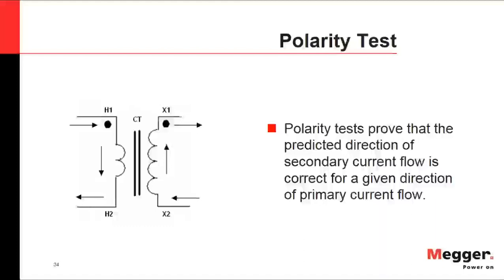or the fault will be created without a real fault in the system. In the metering environment, just imagine that you are power generation and you're transferring energy from power generation down to transmission. And if you have an inverse polarity on your meter CT, instead of sending an invoice to transmission, you're going to be sending a check. So it doesn't make sense, but you need to be clear what the direction of the flow is for you, especially for your protection devices. Be very careful on the direction. So make sure that the polarity is the correct polarity on the installation of your CT.